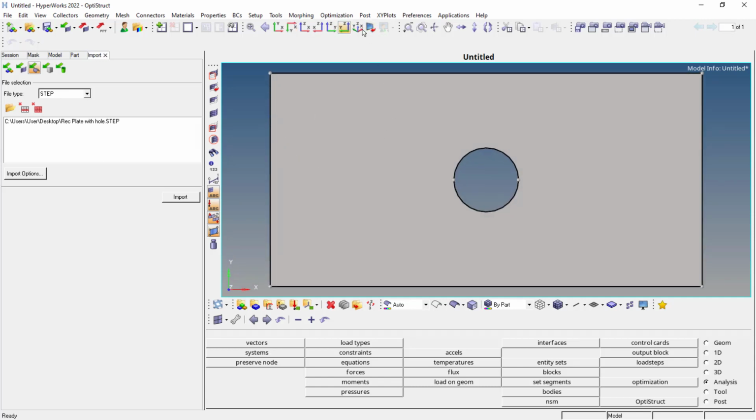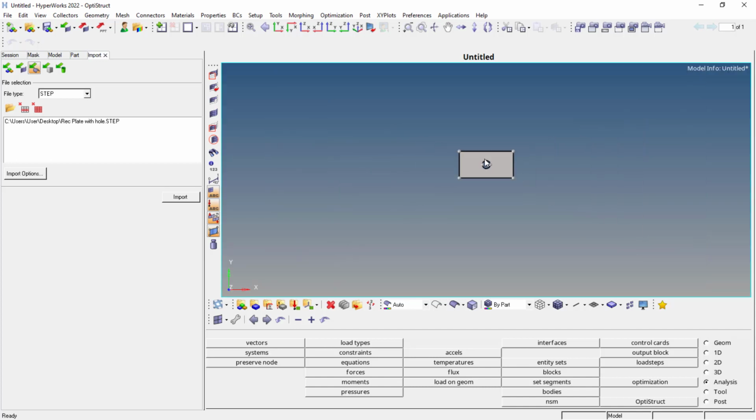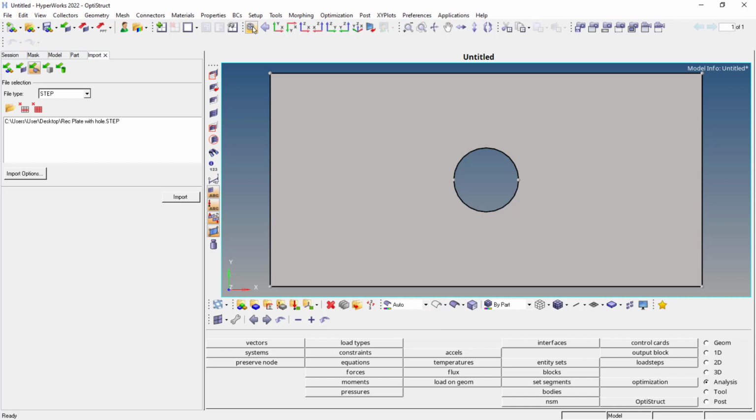Now I hope you got these tools. So this is zoom to fit. So let's say if you scroll away, you can simply press F, or you can click on this particular zoom to fit tool. In this you can split your windows, so multi windows and all you can switch like this.